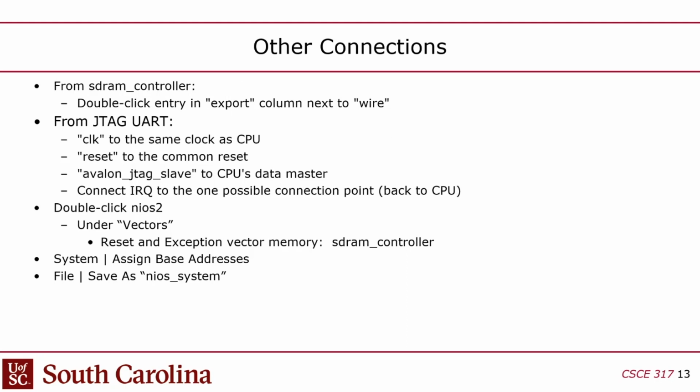And then we add a UART, which is the JTAG UART. Now this is kind of interesting because we talked about UART, and we talked about JTAG, and actually this doesn't even use that, it uses USB. So this thing is a UART that runs on top of JTAG, which then runs on top of USB, somehow. But in the end, what you get is a console on your workstation. So when you print something on the code that you program this thing with, it'll print it on the console. But like I said, it's kind of convoluted.